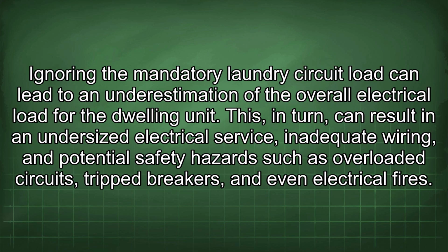Ignoring the mandatory laundry circuit load can lead to an underestimation of the overall electrical load for the dwelling unit. This, in turn, can result in an undersized electrical service, inadequate wiring, and potential safety hazards such as overloaded circuits, tripped breakers, and even electrical fires.